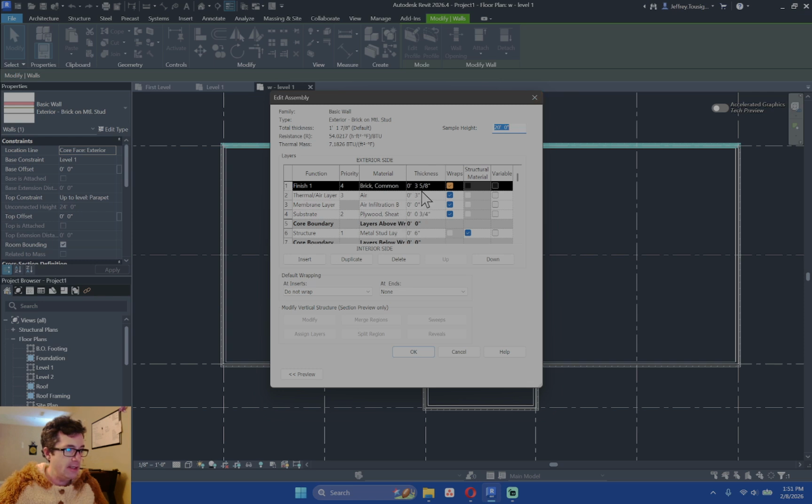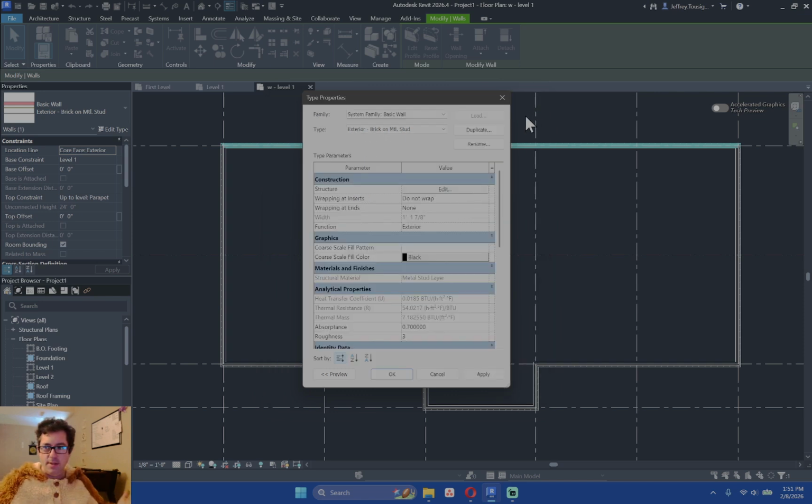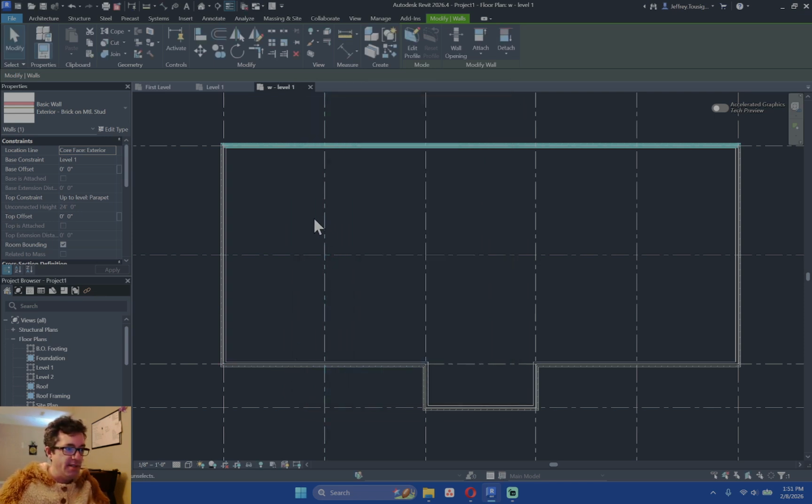But these are all looking pretty good. A little bit high for air value. Probably want to increase these gypsum wall studs to 5/8, but again, I'm not going to put in work on information that we don't know based on assumptions and past projects, because every project can be a little bit different.